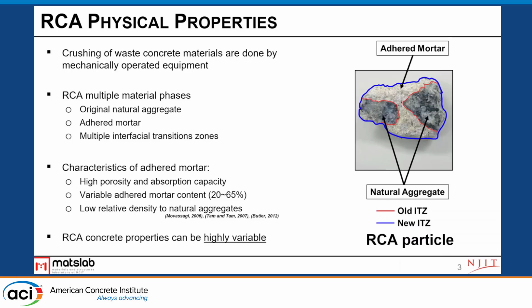And so when you start looking at all of the components that go into performance at the mesoscale level of concrete, you have to consider that the ITZ of the recycled aggregate to the new paste is different from the ITZ between the old aggregate and the old paste. So there's all of these different components to start thinking about. You can't just sort of use a single value for your aggregate anymore in your modeling tools.